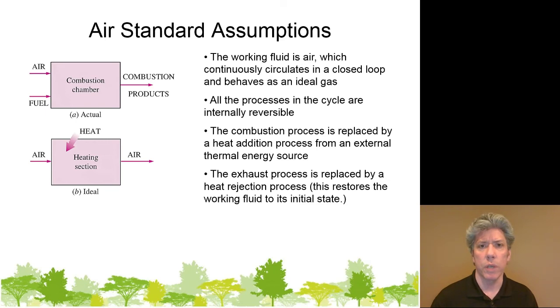Now, that may seem like a pretty far stretch, but if you think about the way the engine actually works, think of the engine in your car, for example. Well, you put air in the cylinder and you put fuel in the cylinder. Any idea how much? Well, the stoichiometric ratio is around 14:1 or so for gasoline. What that means is that you're putting 14 times the mass of air versus mass of fuel into the combustion chamber for that particular power stroke.